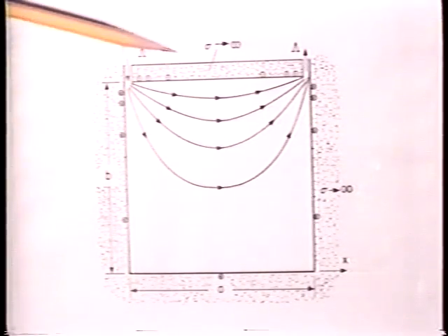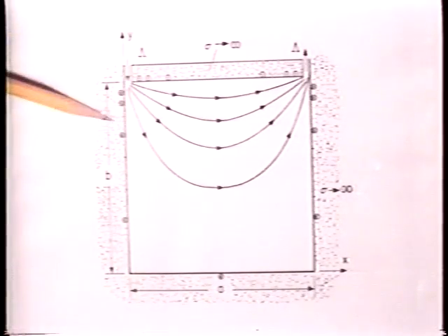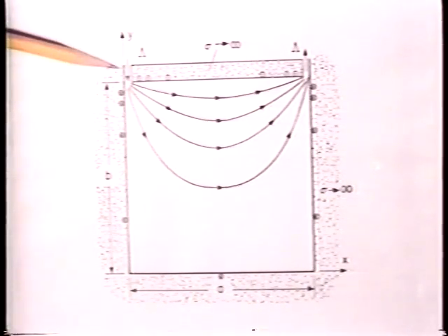This boundary of elevated vector potential is also a perfect conductor. The difference between the vector potential on this electrode and on the wall is the net magnetic flux per unit length passing inward through the gap.